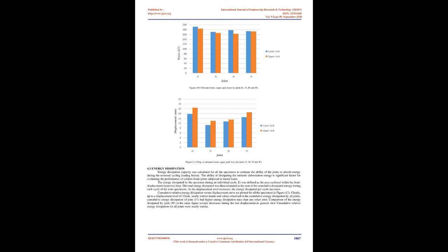The envelope curves were built as the locus of the maximum points belonging to the load displacement hysteretic loops, which contain the peak points from each cycle of each loading step. Small differences in maximum positive and negative loads are due to geometrical imperfections and steel reinforcement disposition.